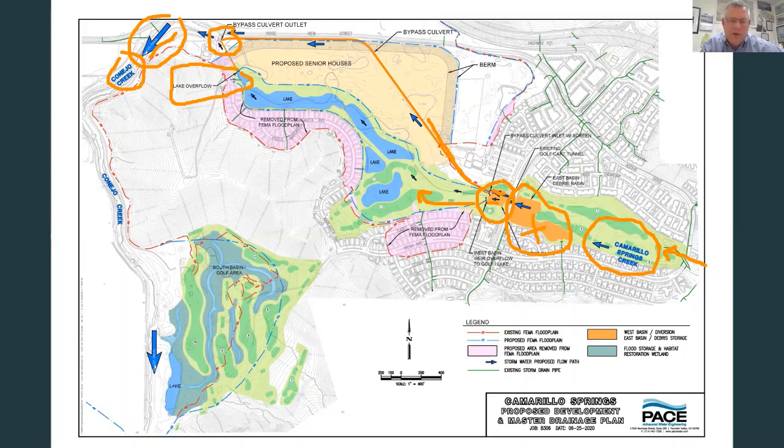And this bypass culvert is 6 feet high and 10 feet wide. So you have a significant 600 square feet of opening to pass flows through. And it has high velocity in there, and so any of the lighter debris that gets in there, leaves and cups and things like that, they'll get washed out. Even with a small flow event, there's high velocity in the bypass culvert to push those through.